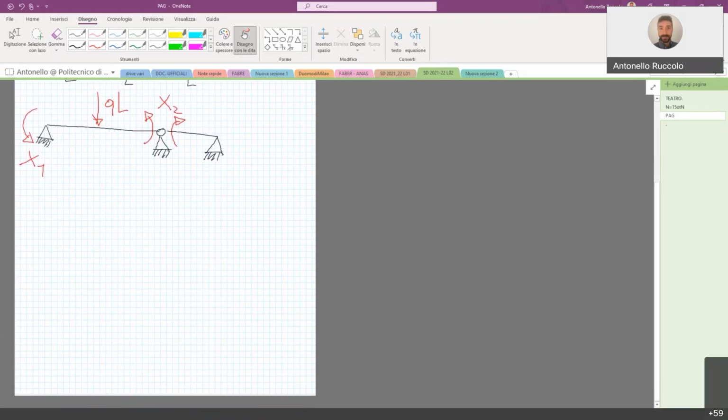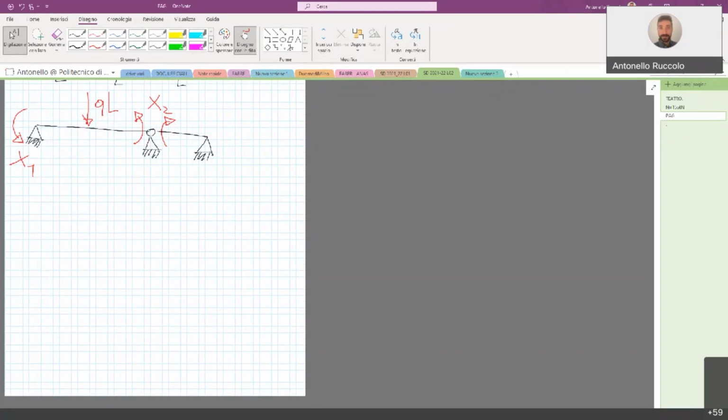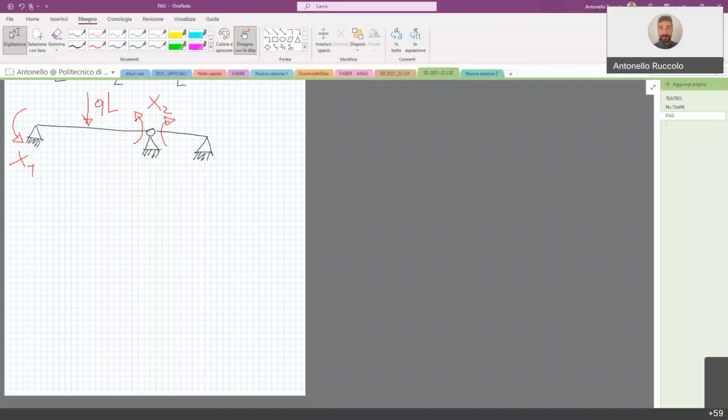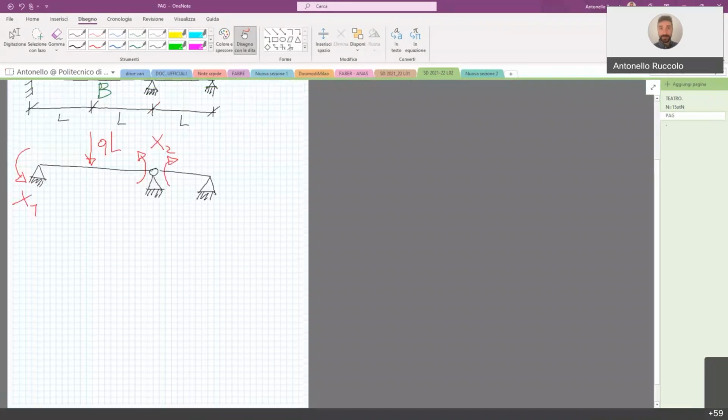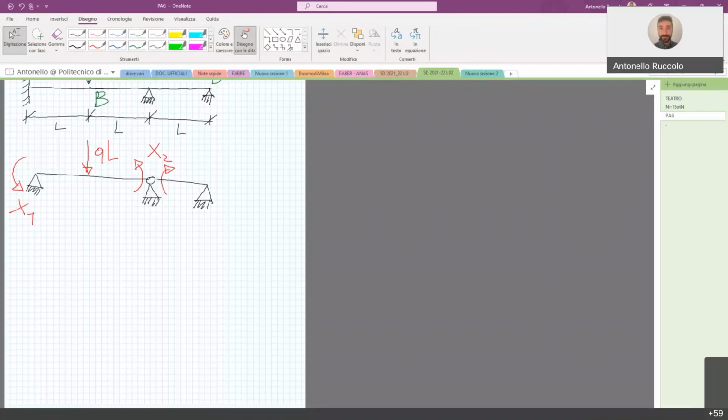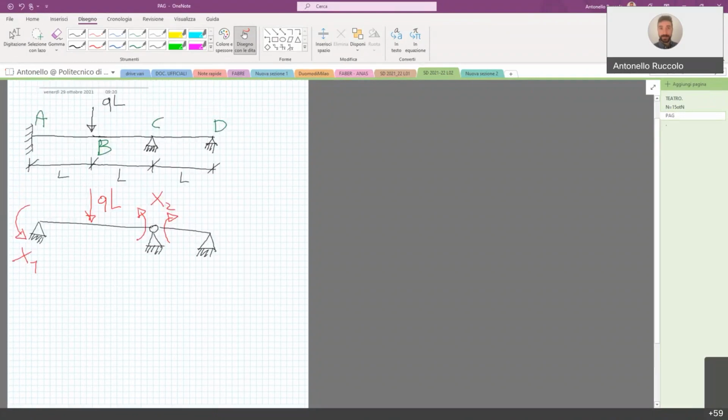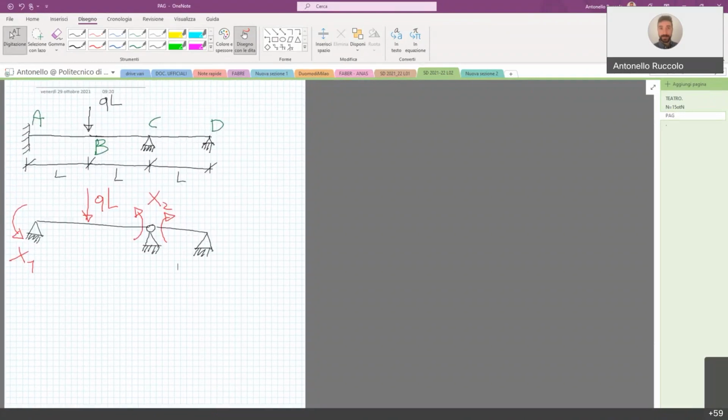And this was basically the theme of the lecture of Gentile last week. Now we are just reviewing it, trying to understand how to apply this force method. The logic is we do not work on the original structure because it is statically redundant, so we cannot solve it using equilibrium equations. We create a second structure which is statically determined, so we have an equal number of degrees of restraint and degrees of freedom, and we can solve it using equilibrium equations.